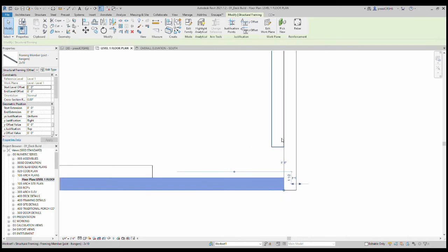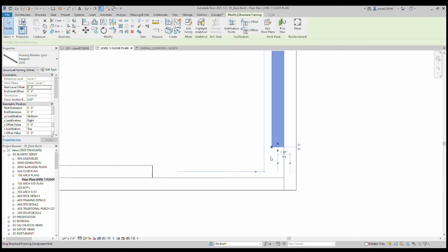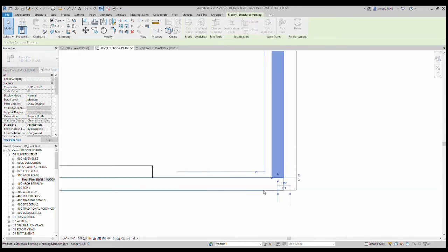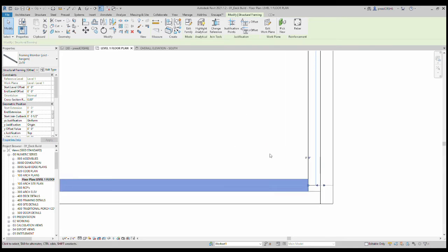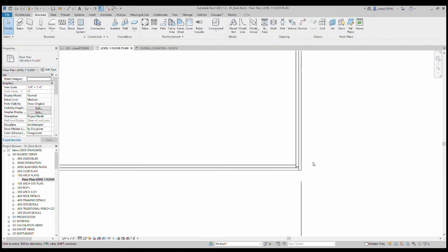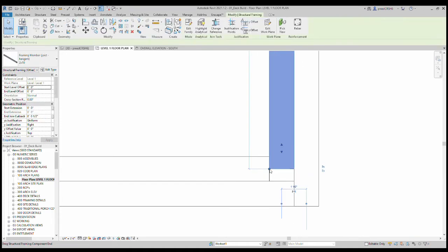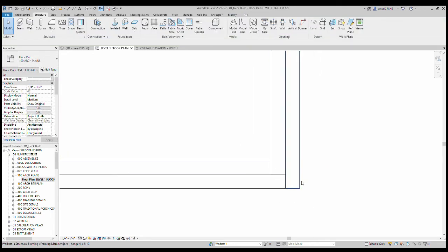So we like to stagger our joints. There's another way to do this if you keep having problems where you have elements wanting to connect to the center and do weird things. You can right click on that blue dot and disallow join, and that'll stop it from connecting to the next beam. Just like that one's doing there, right? So disallow join, we can connect that and drag it through.